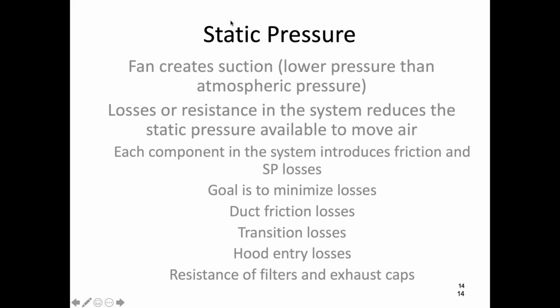So in industrial ventilation, we look at all those different properties, and we can figure out, if I want 100 feet per minute from a 1-inch duct right here, we have formulas that'll help us figure out how big a fan we need 100 feet away after it's made 7 turns. That's what we do when we design industrial ventilation systems. Why did I say 100 feet per minute right here? Because that's what we need to capture the contaminant to keep it away from the worker.